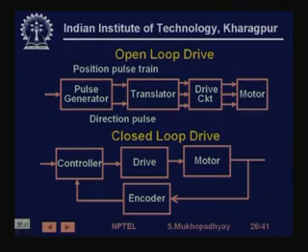On the other hand, if you want to really move it fast, then you need to know whether the pulses that you are sending have actually been executed by the motor. So, you need to take a speed feedback. So, you can have two kinds of drives. For more precision drives, people use a speed feedback.